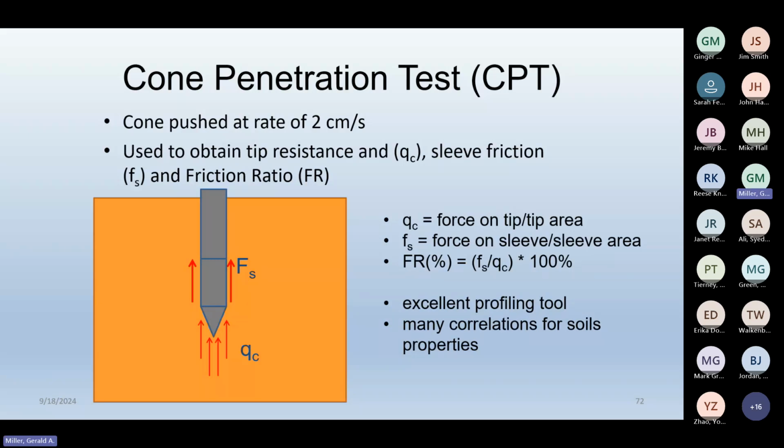It's not that they're useless, but you may recall, those of you who have worked with what we call the piezo cone, which has the saturated porous element, in order for that piezo element to function properly, first of all, it has to be completely saturated, right? With some kind of fluid, silicone oil or glycerin or whatever you're using. And so that means that it really should only be used in saturated soils.